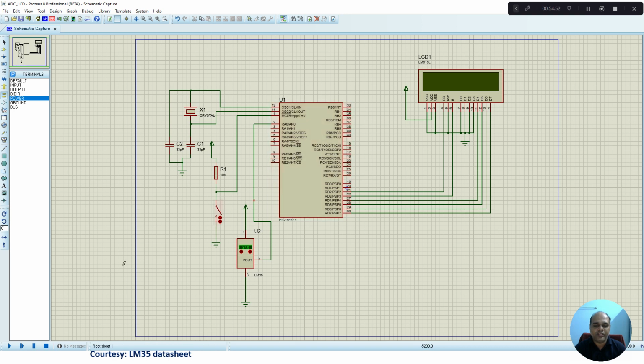Now let us see the logic. You can see temperature sensor interface. Then it shows temperature equal to, in centigrade, 27. Right now the LM35 measures 27 degrees, so it is showing 27 here. When I start increasing the temperature using the arrow here, you can visualize that the output displayed also changes. Now 30 degrees, so it shows 30. I can increase and you can visualize the change in the output value.